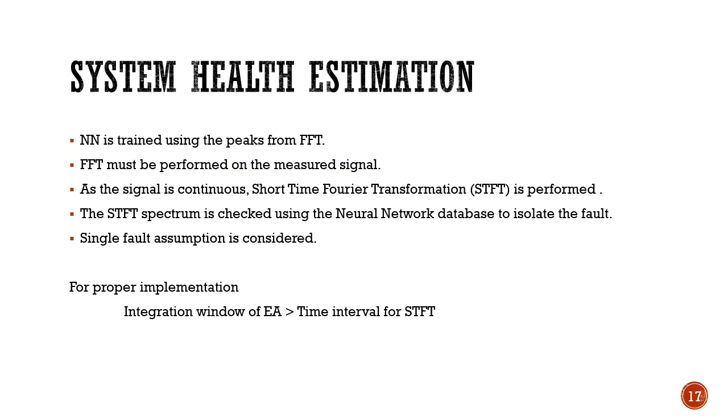Neural network is trained using the peaks of the FFT analysis of residuals. Therefore, to match, an FFT analysis must also be done on the measured signal. As the signal is continuous, short time Fourier transformation is performed. But it must be assured that the integration window for calculation of energy activity must be larger than the time interval used for short time Fourier transformation.